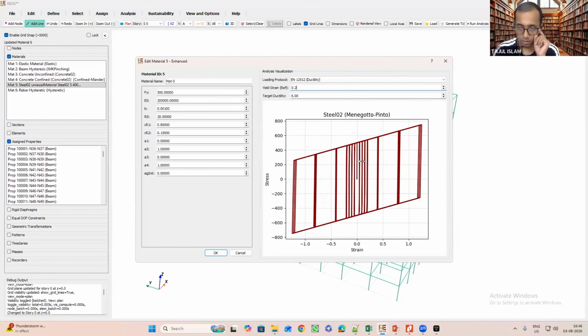So that's why this model is not realistic for earthquake loading assessment. You need some material model which can degrade under cyclic loading. That's why you should not use this model without any cap. There is an option available like min max cap. You can use this, wrap it in a min max material wrapper. There you define the maximum strain as, for example, 0.05. So once this material reaches 0.05 strain, it will indicate failure.